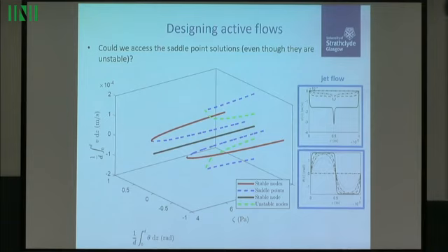I'm going to do that by, again, a bit of physics from the classic liquid crystal display type approach, by using pre-tilt and orienting fields. I can actually get this director structure in a particular way. On one side, I orient my director in a positive direction, and on this side in a negative direction.